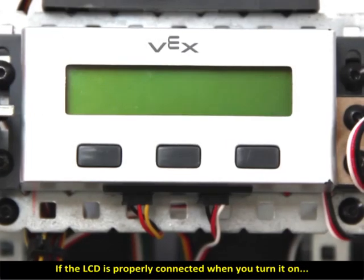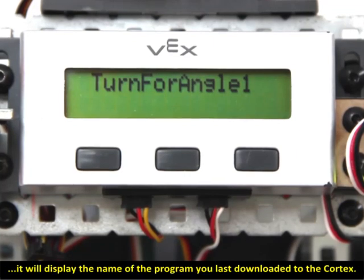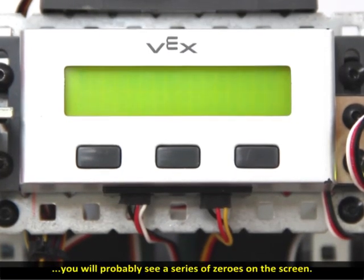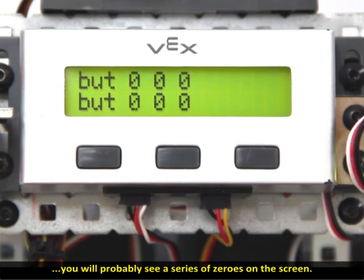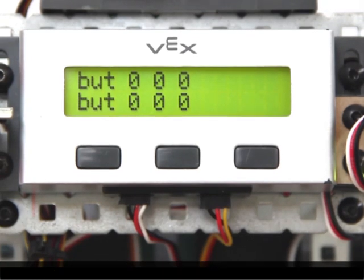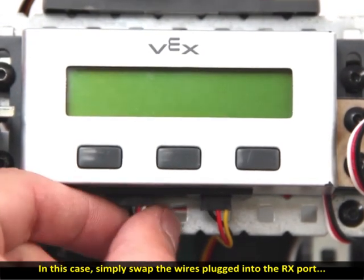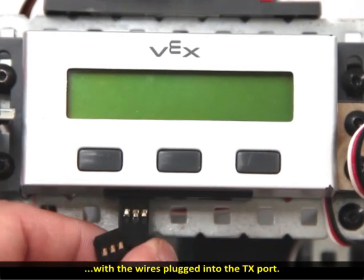If the LCD is properly connected when you turn it on, it will display the name of the program you last downloaded to the Cortex. If the LCD is not properly connected, you will probably see a series of zeros on the screen. In this case, simply swap the wires plugged into the RX port with the wires plugged into the TX port.